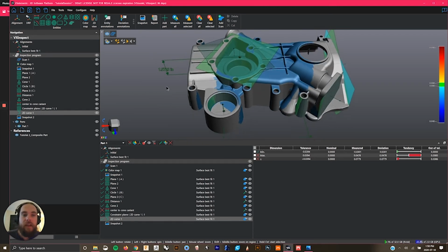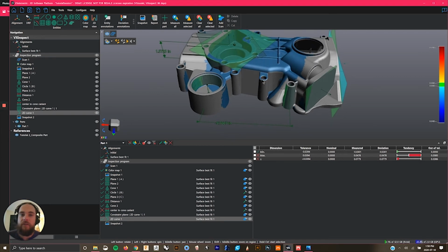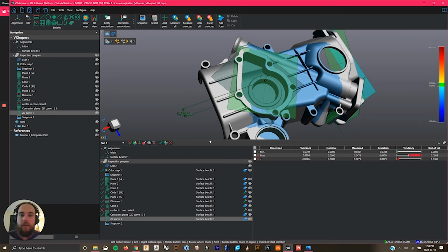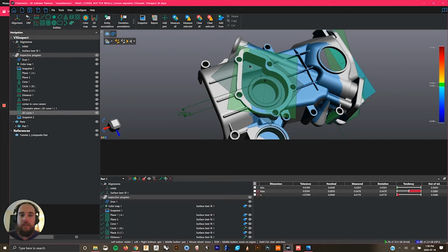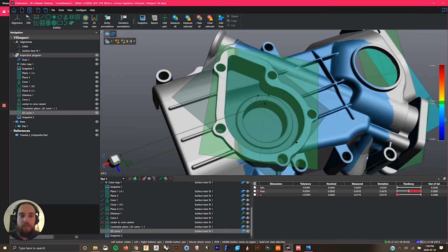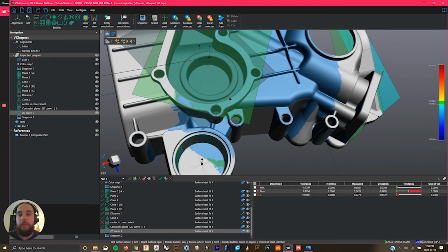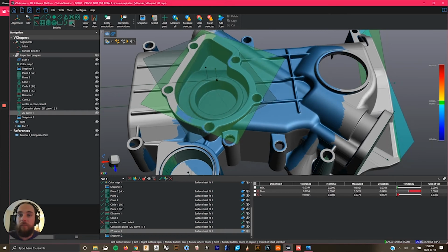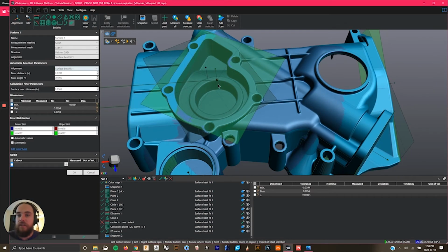There is another way to capture and measure complex surfaces. So for example, what if I wanted to measure the inside surface of this part here and see that surface profile and how well that's adhering? We can certainly do that in this program. So let's go and make a surface. A surface is going to be made up of a selection of different things that will measure off the mesh, which is scan 1, and we're going to pick on CAD using this alignment.